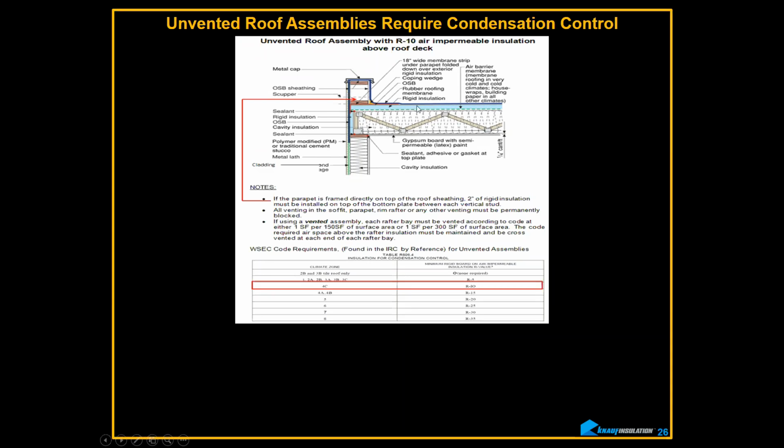And again, it does not have to be impermeable or vapor semi-impermeable like the blue board shown here. It can be anything as long as you keep the sheathing warm enough, 45 to 47 degrees. 45 is absolute minimum. I like 47 degrees. You can keep this at 47 degrees, which is what this insulation is doing.